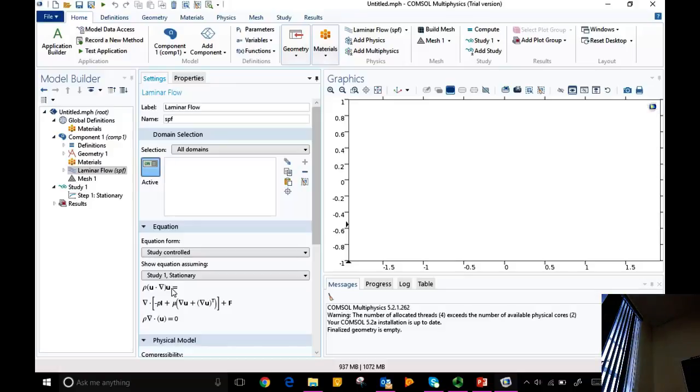It requires us to provide only 2 parameters, the parameters that are lost from the molecular nature to the continuum nature. Those are the density and the viscosity. Gravitational force is known, okay, as a constant for practical purposes on Earth, right? So that equation is valid on Moon, on Saturn, wherever you go. You just have to adjust the appropriate g, right? And if you have the same fluid, it should behave in the same way. So those are the equations that are solved here, right?